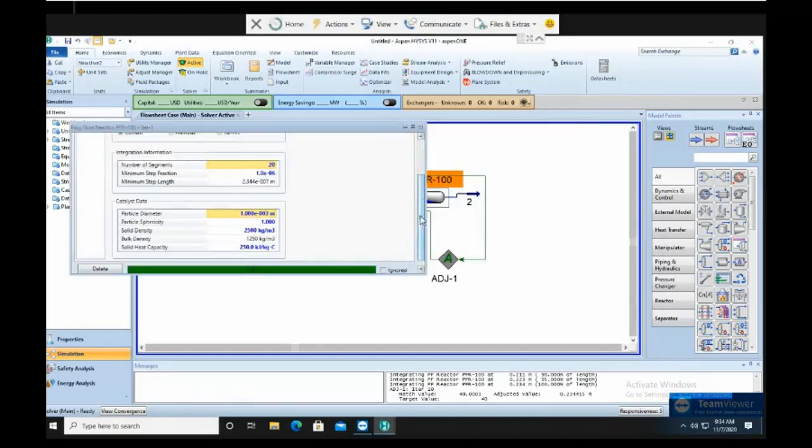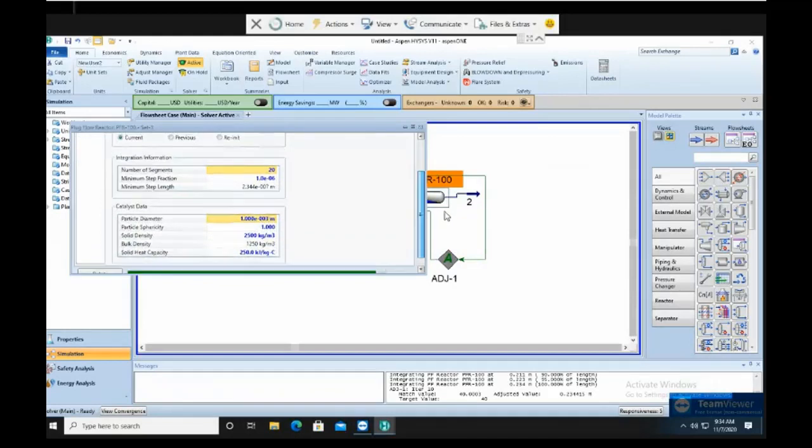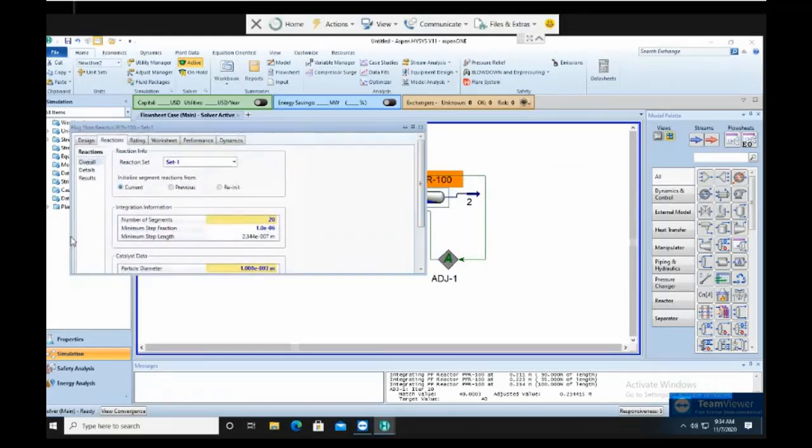If you already know some information, you can set the number of tubes to be, say, 10 or 100. If you calculate it, you can get 100 like that, because you pack the catalyst in the tubes, especially when you want to do a packed bed. For a fluidized bed, there are rarely tubes; usually it's one big vessel. But this is only an estimation. So you got this already.